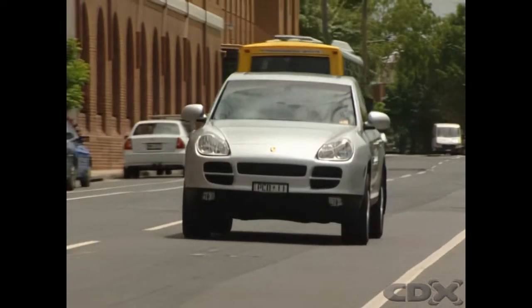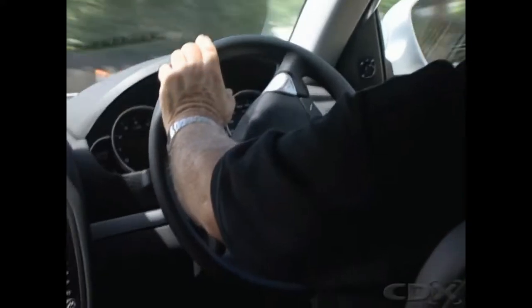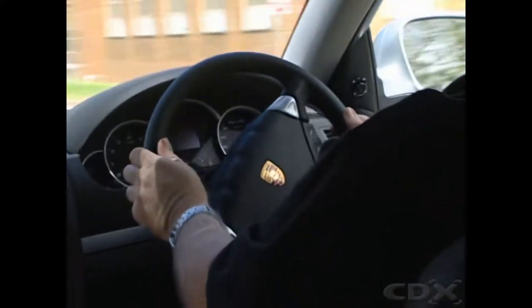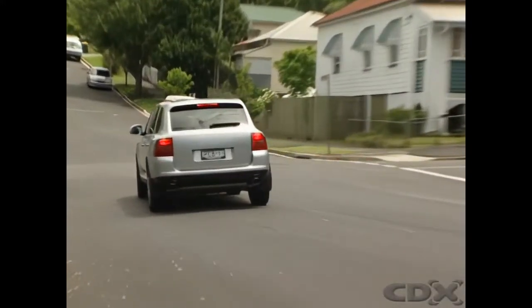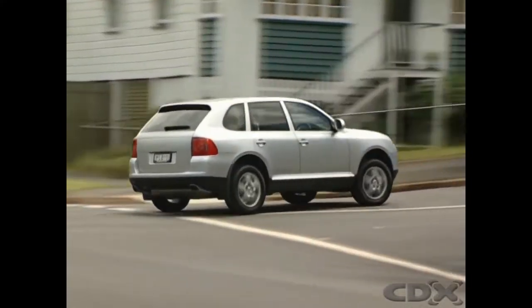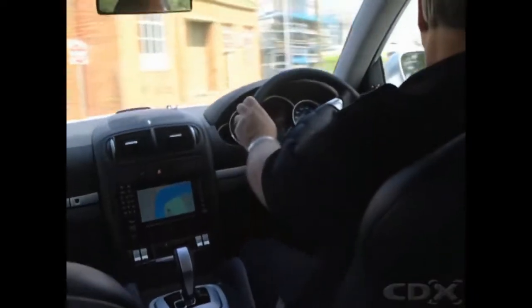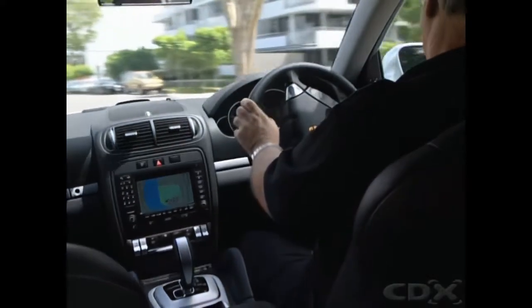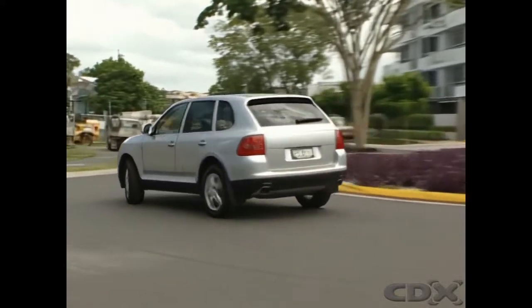computer-controlled. With heavier vehicles, increased use of front-wheel drive, and wider low-profile tires, more steering effort is needed, so power steering is used. An engine-driven hydraulic pump provides pressure that helps the driver steer the vehicle. The power steering system is designed so that the vehicle can still be controlled even if the engine or the power steering system fails.